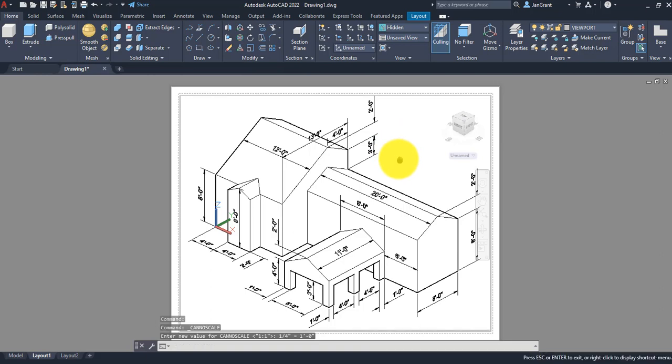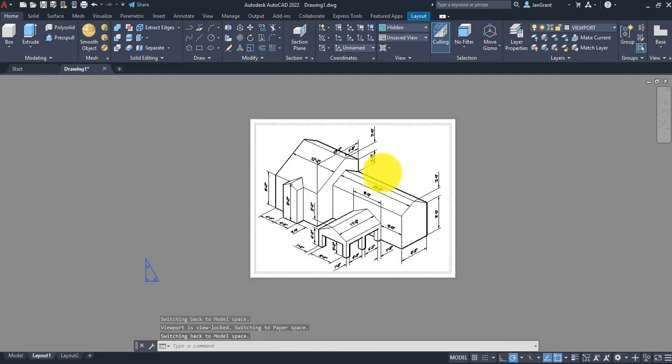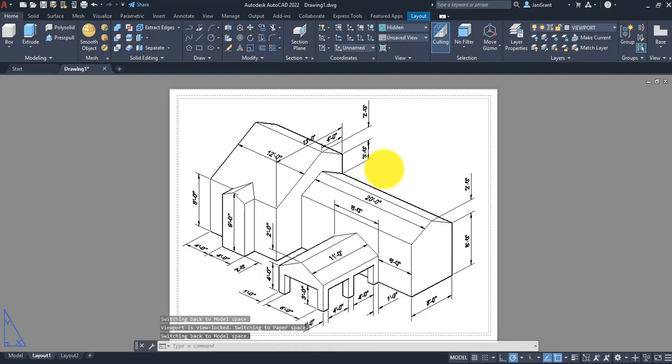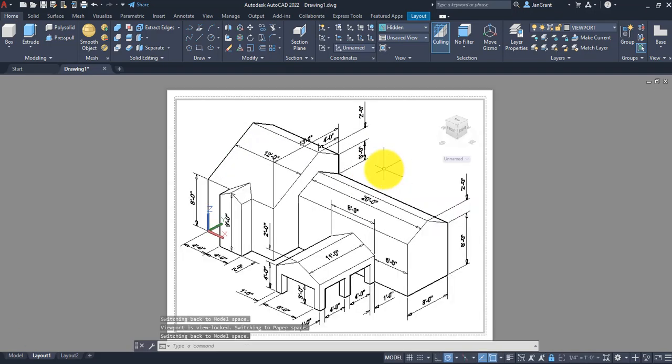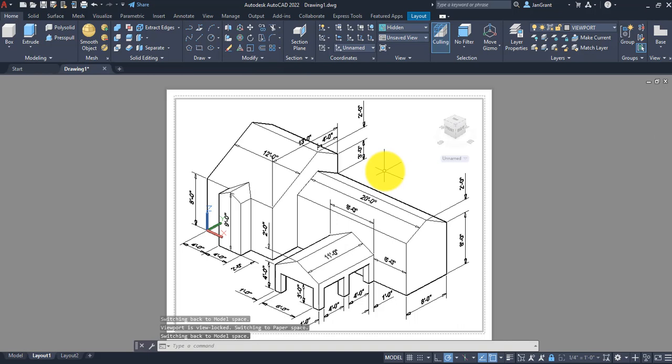That's what we do to specifically create this at 1/4 of an inch right there. There's even a lock icon right here. It says selected viewports are not locked. I'm going to lock it. And the reason, first of all, don't lock it until you know that you've moved everything around where you want it, like what view and all that. Because once you lock it and you zoom inside the viewport, it'll kick you out of the viewport. So it kind of locks in your image.